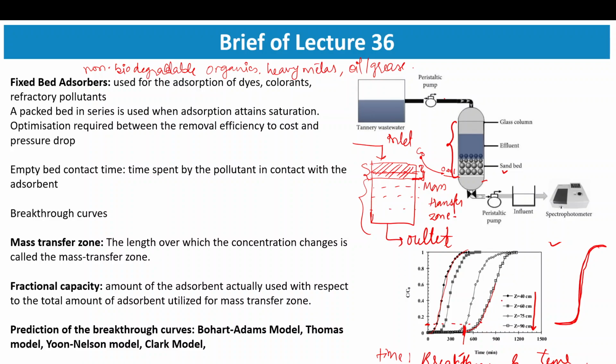Now again, this breakthrough time depends on the contact time or the residence time which the pollutant spends inside the column, right? Or in the fixed bed in contact with the adsorbent, right?